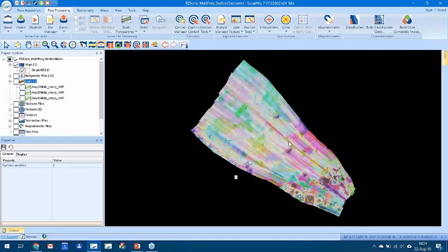Now, this looks bizarre, but if you get used to looking at this, what you know is the red areas are where the low frequency responded strongest to the data, and blue areas are where the high frequency responded strongest. So these are ways to tease apart kind of the sediment or the seabed classification that's down there and help you pull it all apart. It's just a tool we're still working on, but it's available to people who are interested in seabed classification and visualization of different acoustic frequencies.